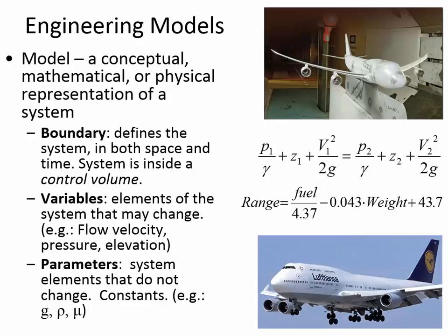It's sort of not the input variables, but just taking, for instance, the unit weight of liquid, or gravitational acceleration, or the viscosity. They may vary a little bit because of changes in temperature, but they're not the main things we're trying to predict with Bernoulli's equation. The things we're trying to predict would be elevation, pressure, and velocity.